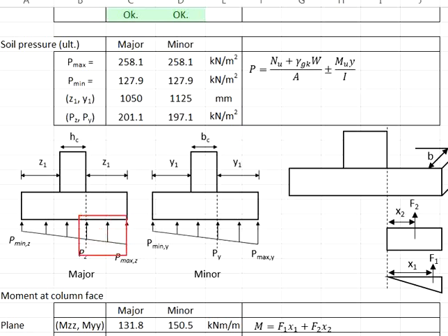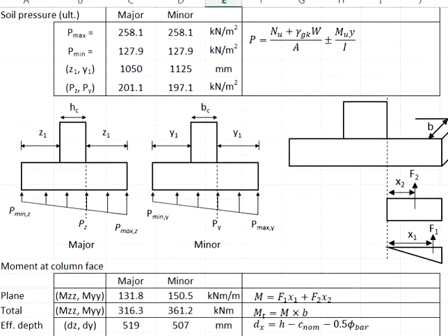The stress appears in a trapezoidal shape. Get the area of the stress and the centroid of the area, which will be the location of the resultant force. To make it easy, the trapezoidal stress area can be separated into a rectangular shape and a triangle shape.